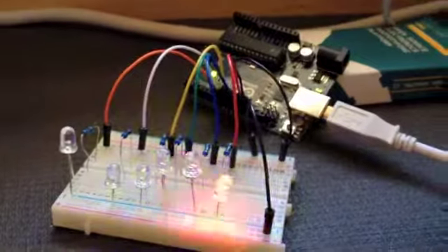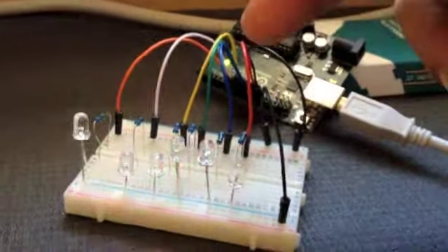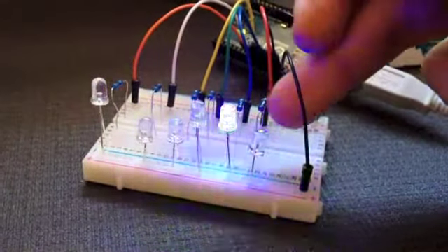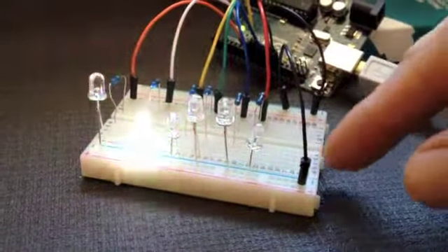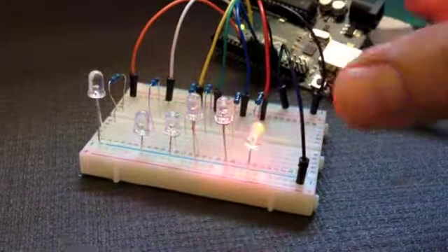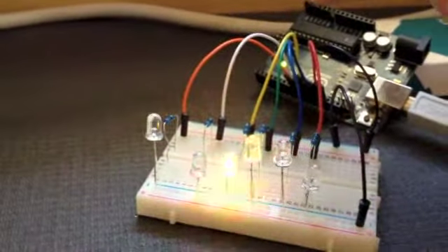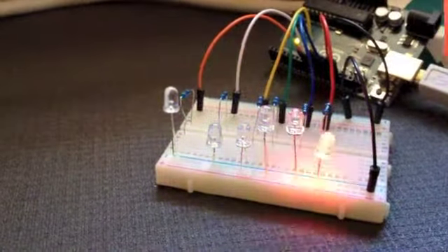So what I did was I took the pinout from the Arduino board, ran it to the positive terminal of the breadboard, ran a resistor, and then to the LED light here at the end, and then it terminates with the negative. So it's just a little circuit, and because each of the pinouts is controlled by the microprocessor, I'm able to control the timing of the lights.